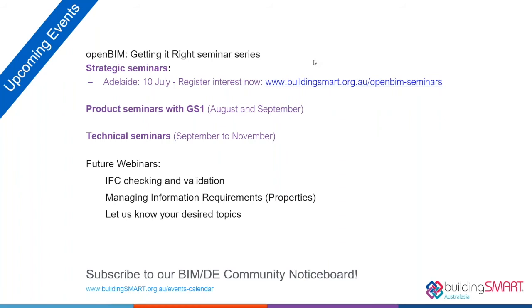Again, buildingSMART can listen to demands and requests and suggestions about how you'd like to see IFC produced, but a typical workflow at the moment would still probably produce DWG or PDF 2D drawing viewports, and then the 3D model for use in IFC with the extra attributes and relationships for more sophisticated workflows.